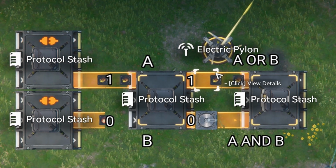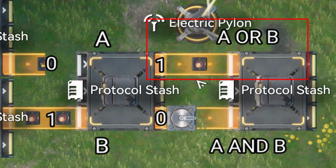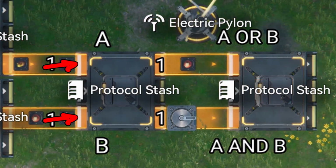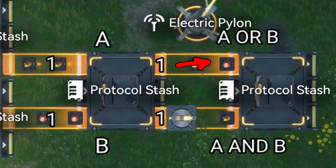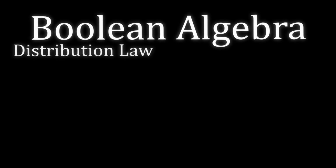I also realized that the redundant signal of an AND gate can also be used as an OR gate. If either of the inputs is on, they will always output to this signal. We can use this to our advantage to save up space.